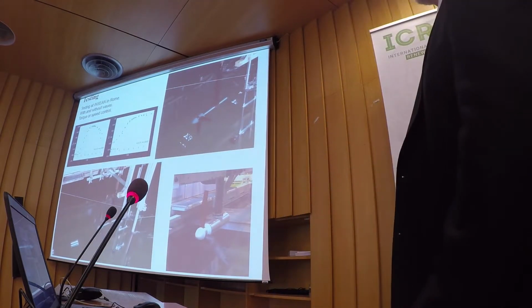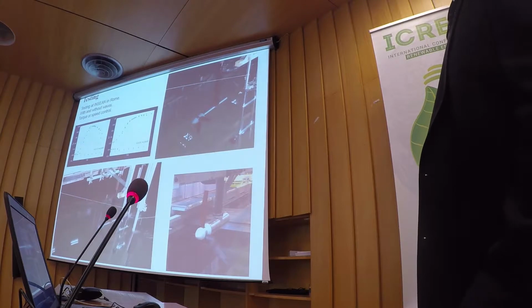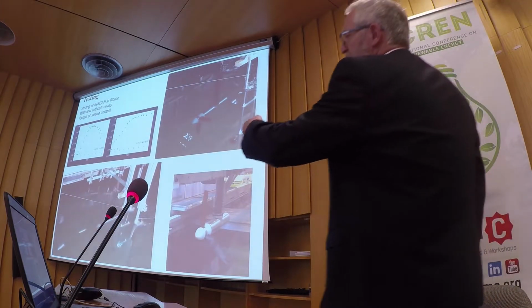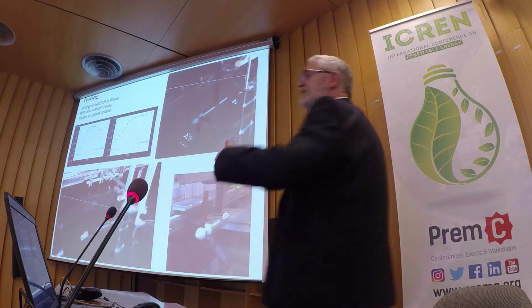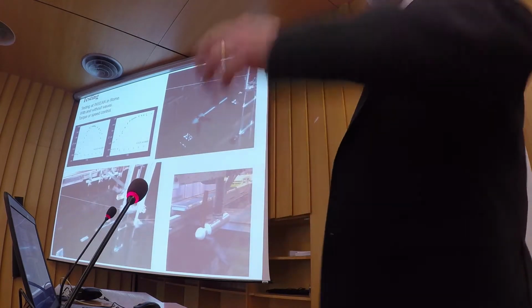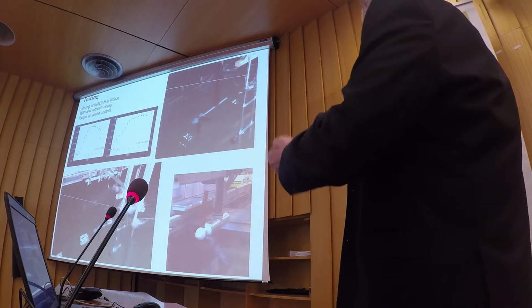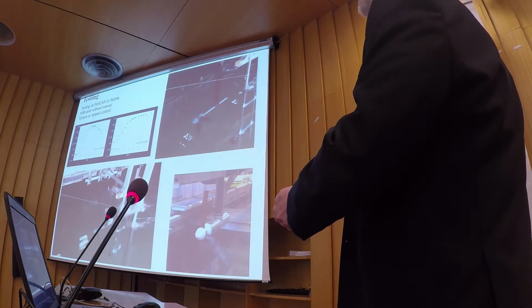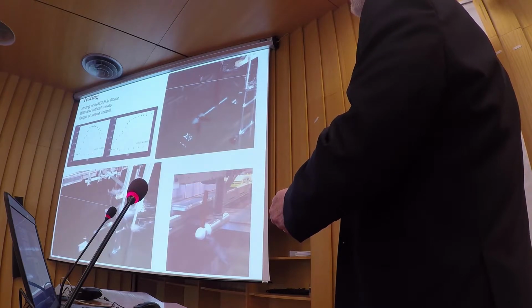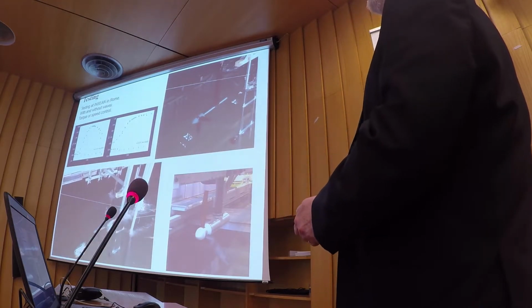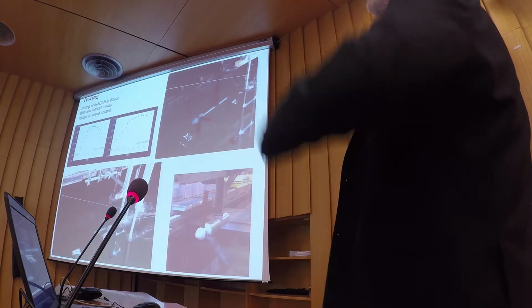So this is about a 4-meter wavelength. If you operate in torque control, the speed of rotation will vary depending on the velocity. If it's at speed control, it will stay constant. So the problem is when you have a tip-speed ratio, if you're in constant torque, this will actually move back and forward. If you're in constant speed, your torque will vary.